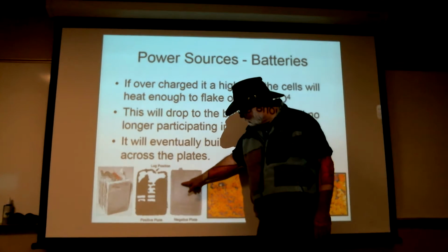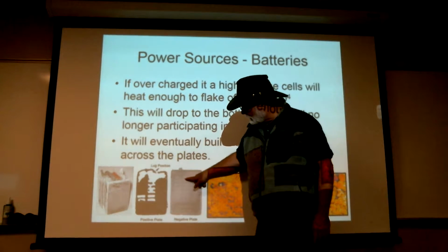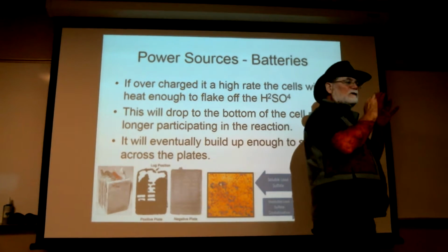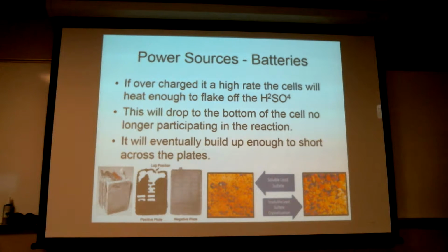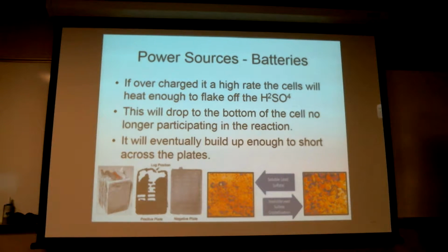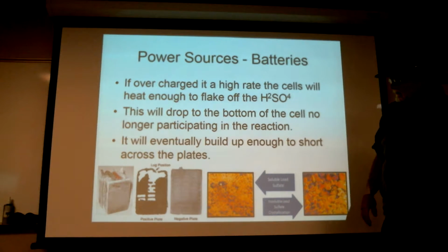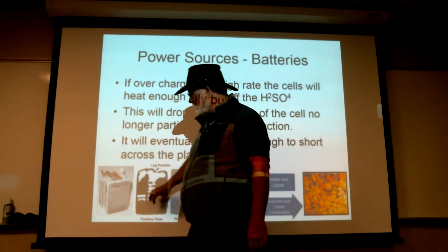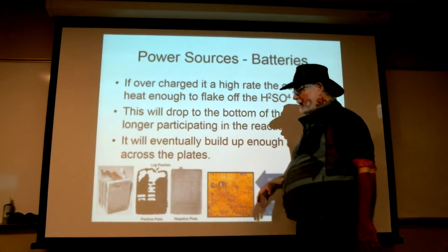It's got sort of a rigid grid work, and then in the middle, they've just taken a bunch of threads of lead or lead peroxide and mashed them into a sintered, sort of porous material and stuck it in there, right? It's not held in there all that strong. So if you start heating things up to a fairly high temperature, you can start causing the battery to break down. You can also get it so hot that it swells up and cracks the case.